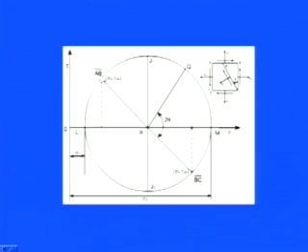So here, if you want to check the coordinate of AB bar, you have the two values of sigma y and tau xy. If you want to calculate the coordinate of BC bar, you can simply plot those, the sigma x and tau xy. So once you have these two points, put those points here with those coordinates. You have sigma x, sigma y, tau xy. So put these values here, fill up those things, get the values of sigma 1 and sigma 2, get the value of P.